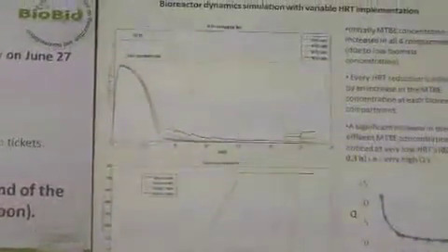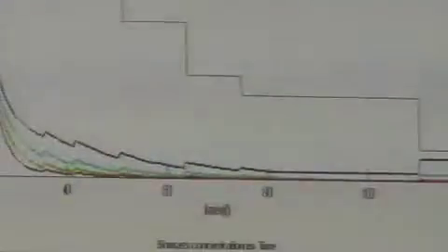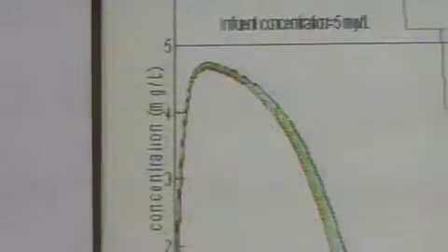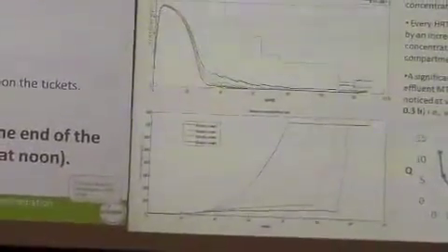After every step, we decreased HRT gradually in a stepwise fashion, where every HRT reduction is followed by an increase in the MTB concentration in all 4 compartments. But we have very high increases at the lowest HRTs, which are 0.6 and 0.3, a significant increase compared to the others. This is because at very low HRTs, as you can see here, a small decrease in the HRT results in a very big increase in the volumetric flow rate.